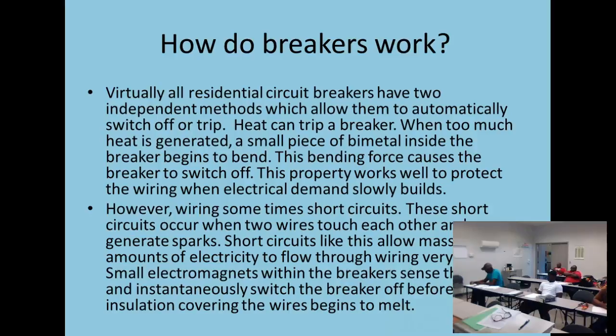If I didn't have it, I'm going to cut it off. I'm going to take these wires loose, put it back on, and check for voltage. If I've got it, you've got a circuit problem. If I don't have it, it's probably the breaker here.